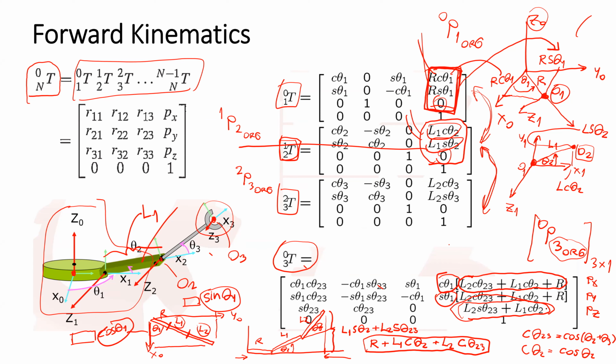Of course, if the robot is not that complicated like this, you may obtain the forward kinematics by the method we learned today, or you can just check the projection of the dimensions like here, the simple way to do it. You don't need to compute the matrix.